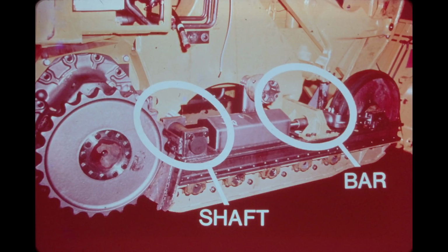The rear mounting for the undercarriage consists of a shaft mounted to the front frame on both sides. The rear of the track frames are secured to these shafts by round brackets welded to the top of the track frame. A retaining link fits into a notch in the ends of the shaft and is bolted to the outer bracket to keep the frames in place.